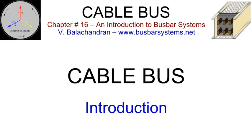Cable bus is an approved assembly of insulated conductors with fittings and conductor terminations in a completely enclosed ventilated protective metal housing. Cable bus is ordinarily assembled at the point of installation from the components furnished or specified by the manufacturer in accordance with instructions for the specific job. The assembly is designed to carry fault current and to withstand the magnetic forces of such current.